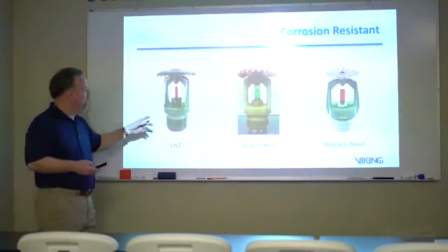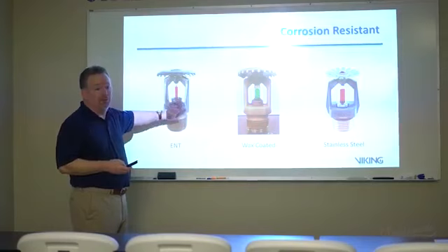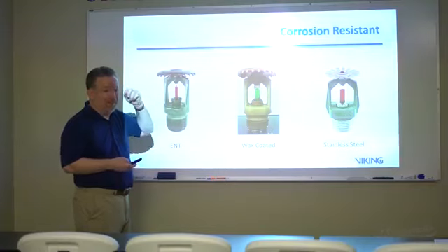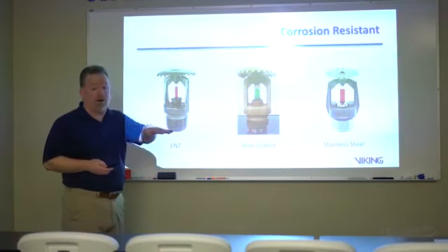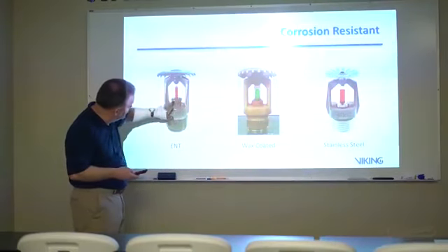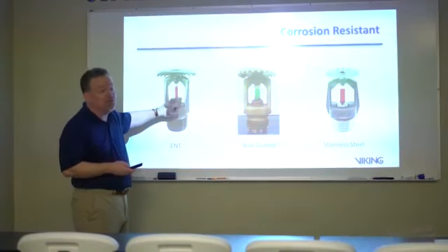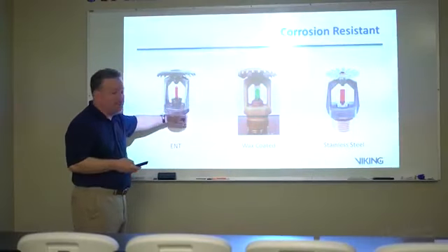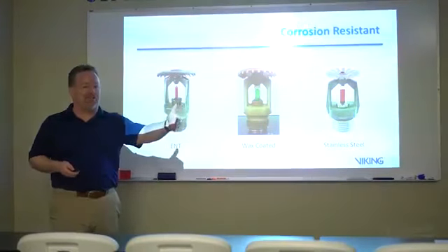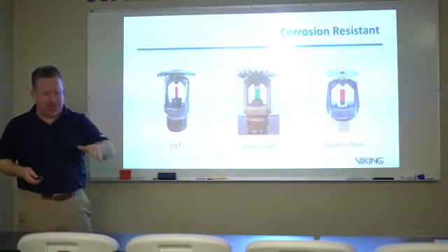Yeah, we've had issues at a university up in New York where it wasn't the environment, it was the water supply. It was a private water supply for this university. It was corroding the head, actually up into the pipe cap and everything, and so they were experiencing leaking. One of the ways we determined that it was the water supply as opposed to anything else is because there were 3 different manufacturers' sprinklers in this particular space being fed by this water, and they all were experiencing the same corrosion.